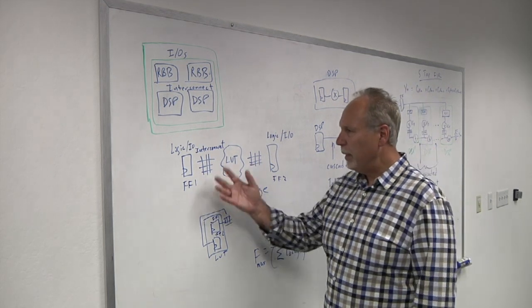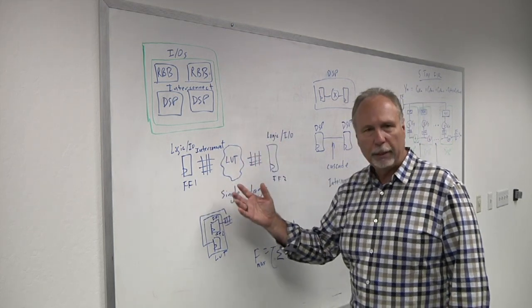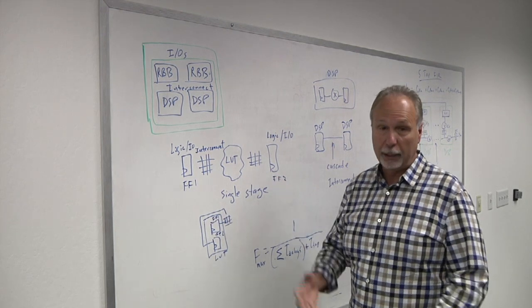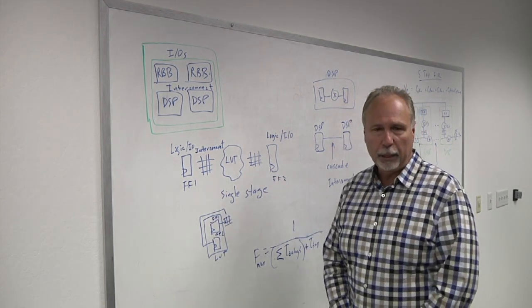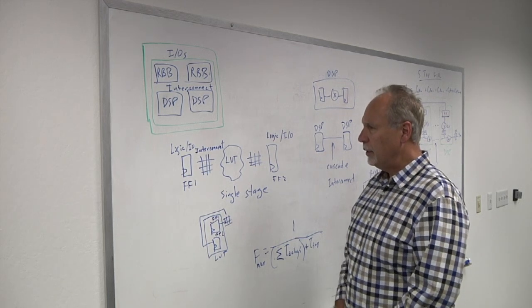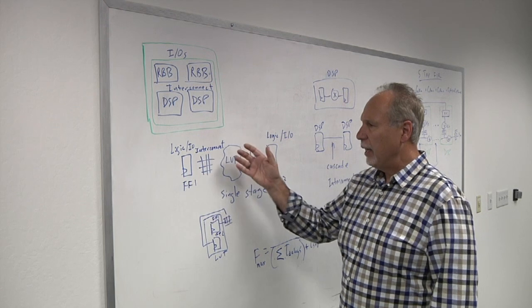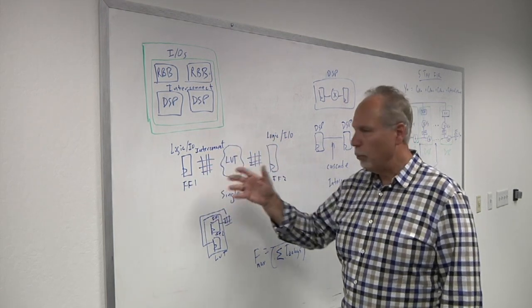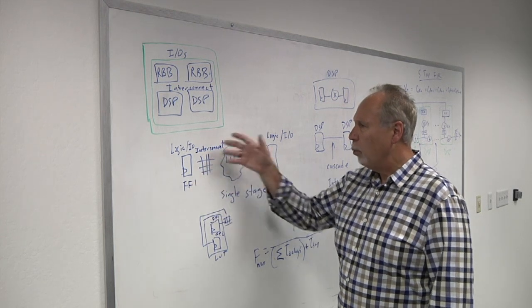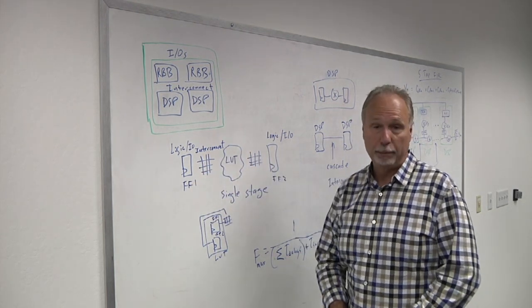Well, in the embedded FPGA, the interconnect fabric is more architectural than it is physical. The physical does impact the speed, but more than the physical is the actual architecture. How fast can I go from one logic element to another? How can I route a signal from one place to another and have the shortest route, basically?